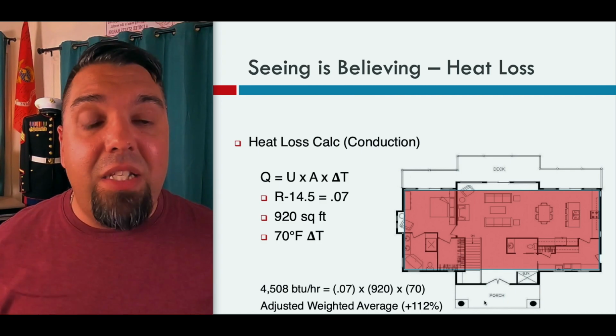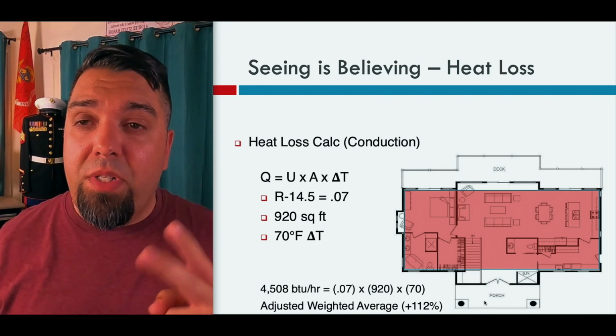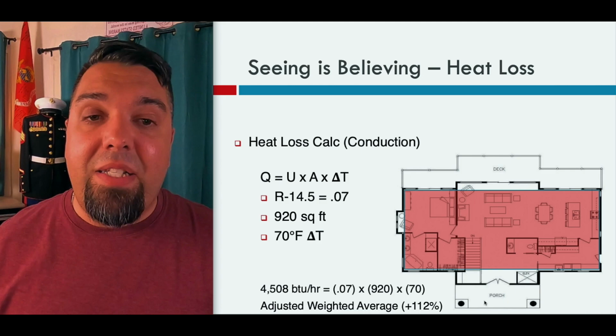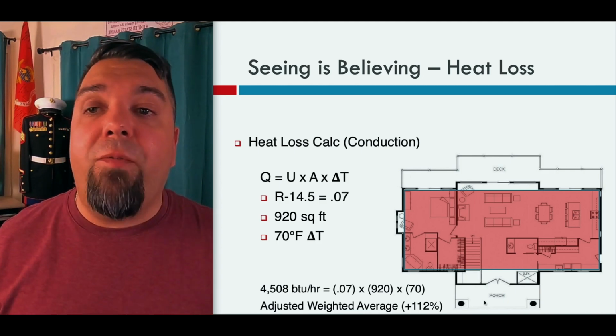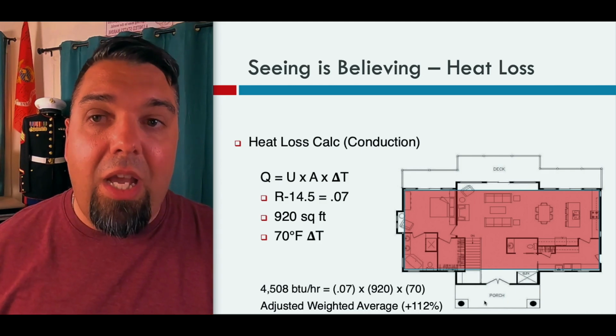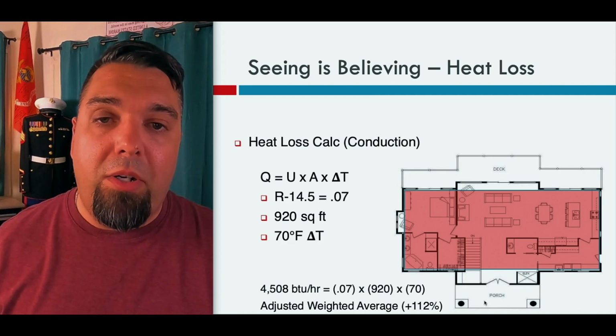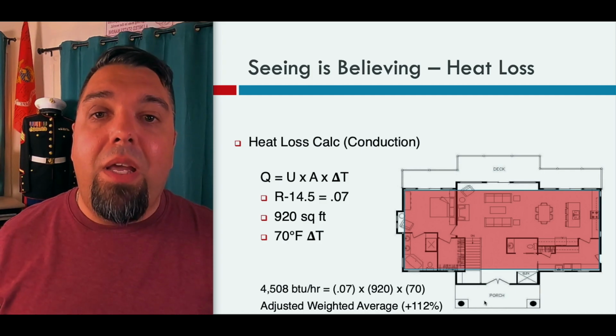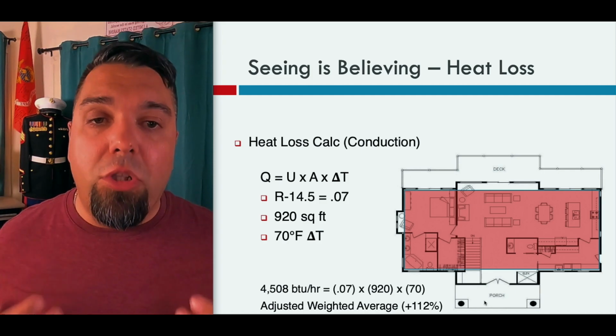And if that insulation isn't installed correctly and we just have 2% air voids in that insulation, we could easily miss what would be half the heat loss of that ceiling. And no wonder it's cold when it's 0 outside in those rooms. So really important you take the time. Seeing is believing. You have to look in the attic.